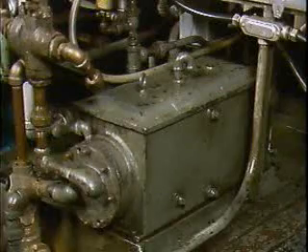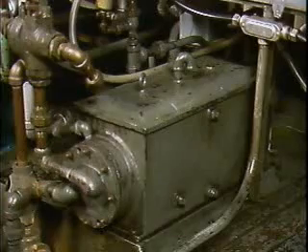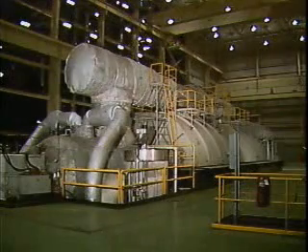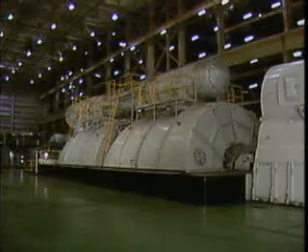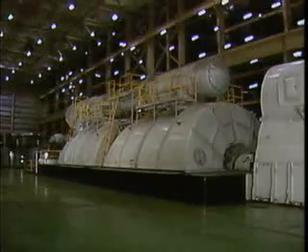The circulating oil group also includes hydraulic oil. Hydraulic oil is primarily used to transfer force from one component to another in a system. Sometimes, though, the same circulating oil is used for both lubrication and hydraulics. For example, large steam turbines are often built to use the same oil for lubrication and for hydraulic control.